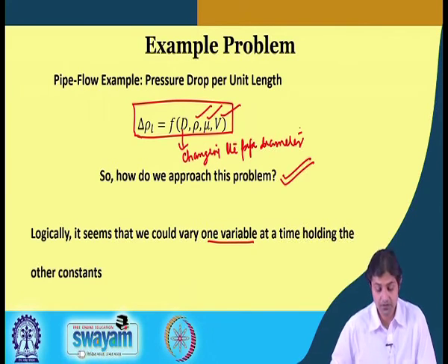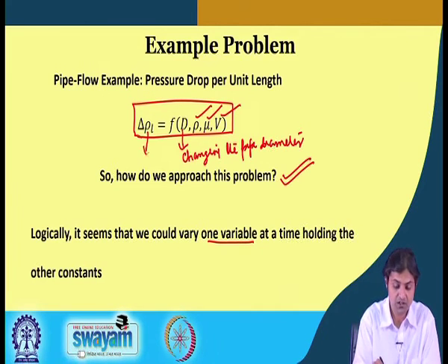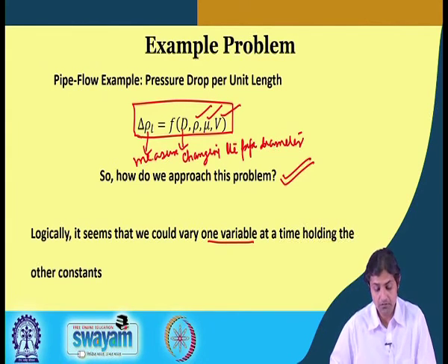Okay. This is one, and we keep everything else constant and measure this. Some other experiments could be, we can start varying the density of the liquid, we can use a different liquid altogether. So that will change its density and kinematic viscosity as well, and the other set could be, we can actually change the flow velocities and keep on conducting many experiments, right.